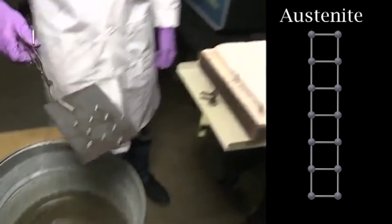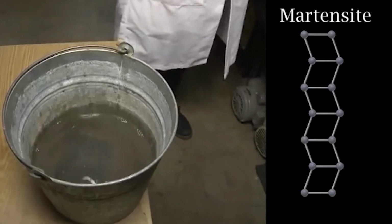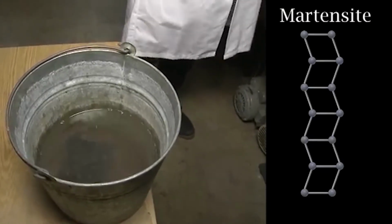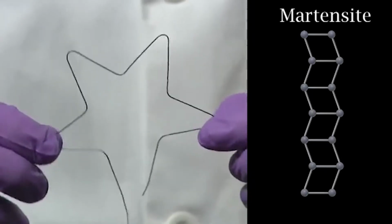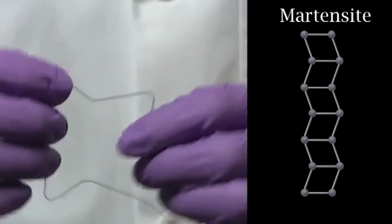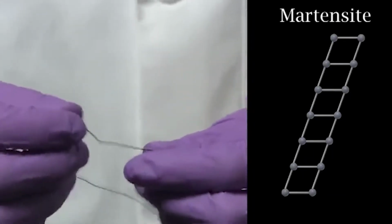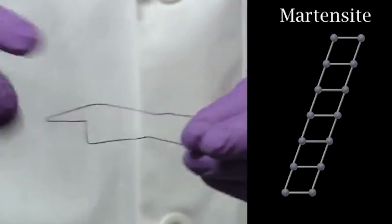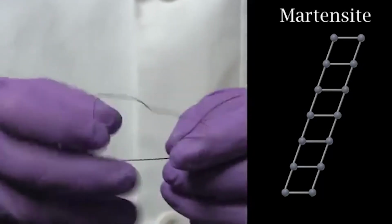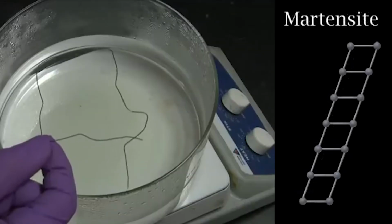When we cool it down, it transforms into martensite, but it does so without changing the shape. In the graphic, you can see that the atoms have the martensite structure, but they align in a zigzag pattern so that the overall shape does not change. Now we can bend the wire however we like. The material does not change phase, but the alignment pattern changes slightly so that they align in one direction. This results in a permanent shape change.